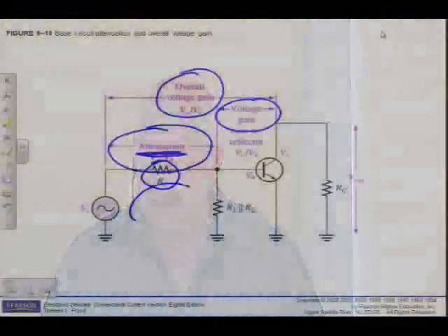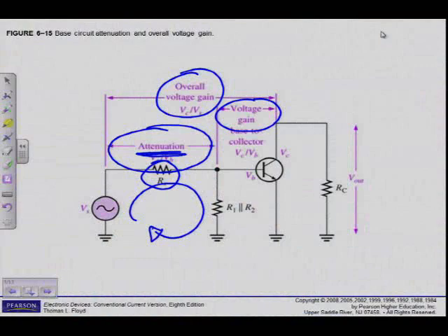Alright, then we've also discussed, when we simplify that, if there's an RS, what happens? Can you remember? We looked at this part of the circuit here, which was a simple series circuit with two resistors, and the two resistors act as what? A voltage divider, no? A voltage divider for my source voltage. Remember my source voltage?